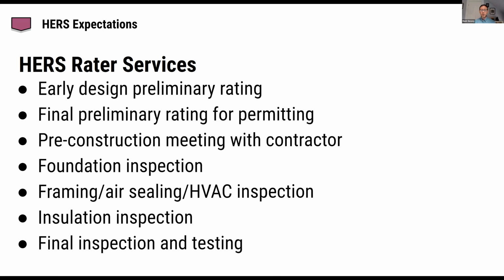They range from one person in their car driving around to large companies that might have 20 HERS raters providing these services. And the minimum needed to do a HERS rating is that you got to calculate some areas, type a bunch of data into a computer software program, look at the house when you insulate it, and test the house at the end, like a blower door test, for example.